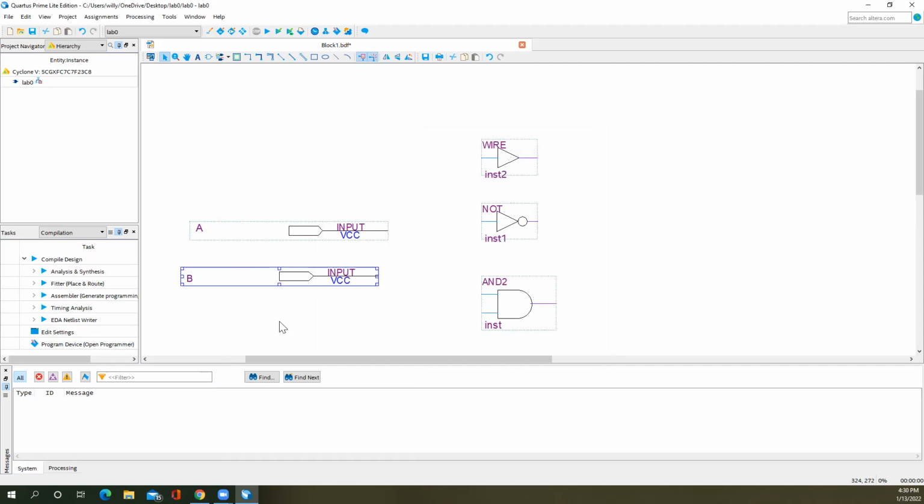When you name your pins, name them with letters of the alphabet, upper or lowercase. I'm using uppercase today to make it a little bit easier to see. As you'll see when we name the output pins, you can use multiple letters, numbers, and if you want to separate words, you use an underscore to do that. So the underscore is the only special character that you can use in the pin name. If you use spaces, hyphens, or any other special characters, it will cause errors.